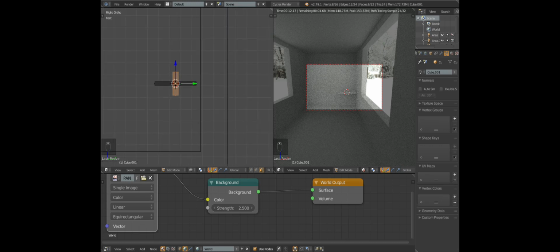We can zoom in here so you can see it. What it's doing is dividing all the surfaces. And here, I'll hit E to extrude. We don't really want it to move, so essentially it's an extrusion. We're going to press Control R to cut, and we're going to pull this up so that it's roughly right.